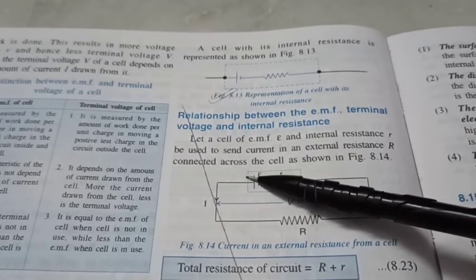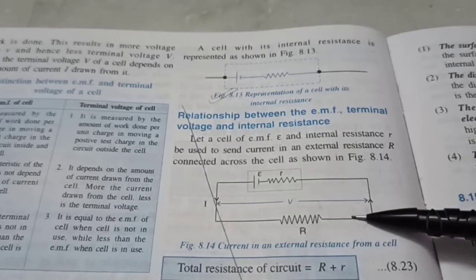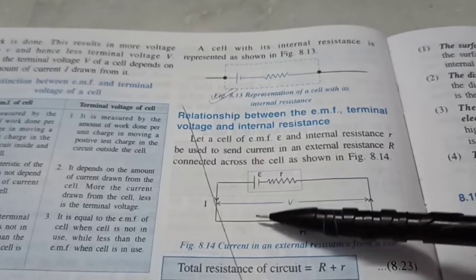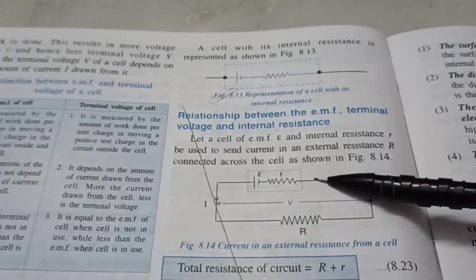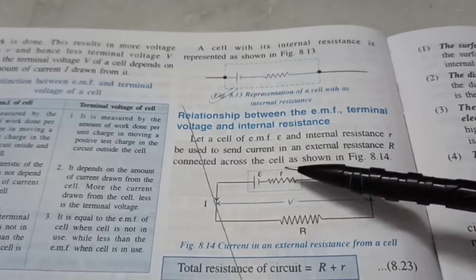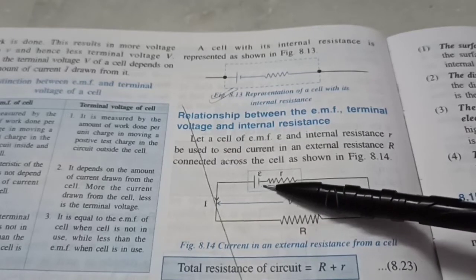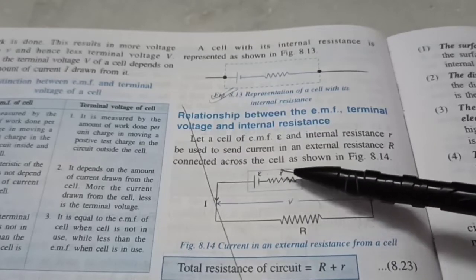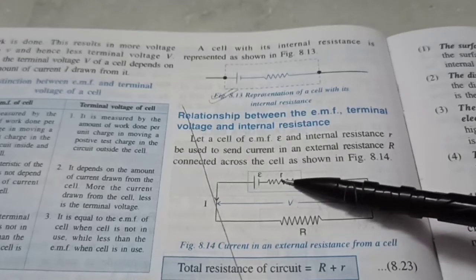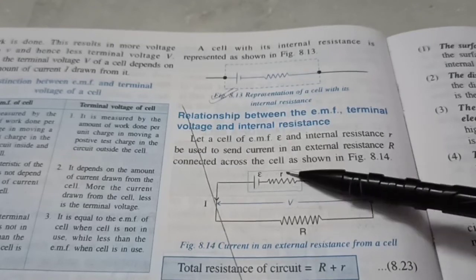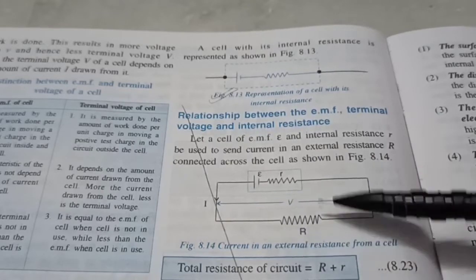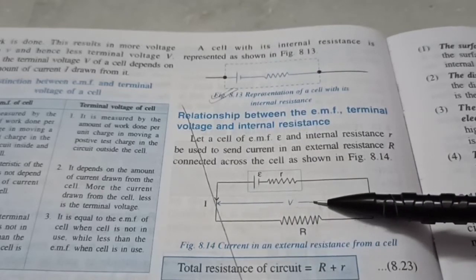So the work we get outside is a little less, or you can say that we won't get the entire 6 volt, we will get say 5.8 volt in the entire circuit, which is still fine because 0.2 volt is not a huge drop thanks to the small internal resistance in the electrolyte. So the voltage drop due to the small r was how much? 0.2 volt. That's right, that's called the voltage drop. And 5.8 volt, that's called the potential difference in the circuit. If you add them, you get 6 volt.